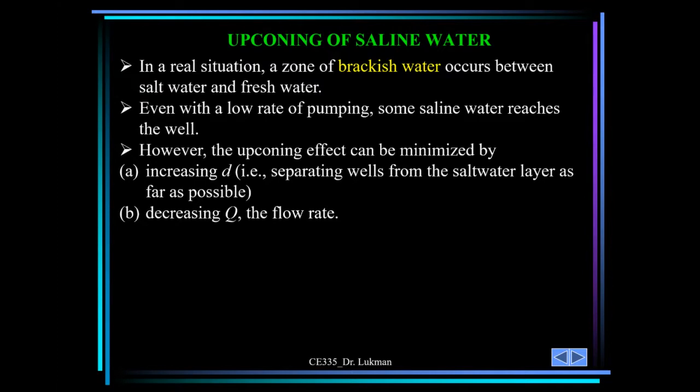But even with a low rate of pumping, some saline water reaches the well. Meaning, even when you find the maximum rate at which you will pump the water in the previous slide, you still find that some saline water reaches the well. And like I said, this explains why most of our borehole waters, our well waters, are pumping saline waters. Sometimes when you taste water from the tap, you realize that it is terribly saline.